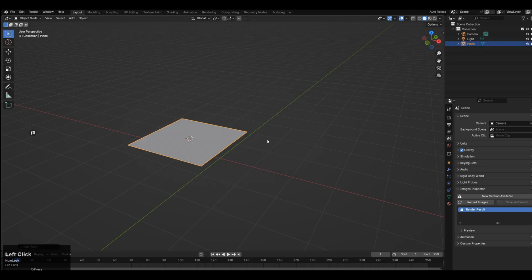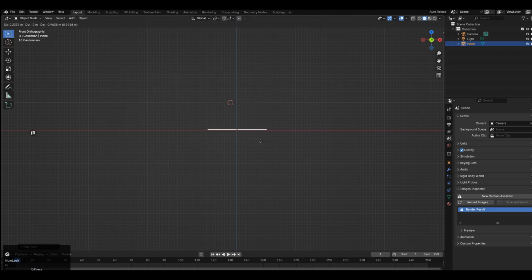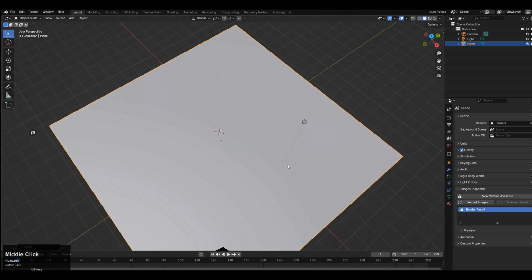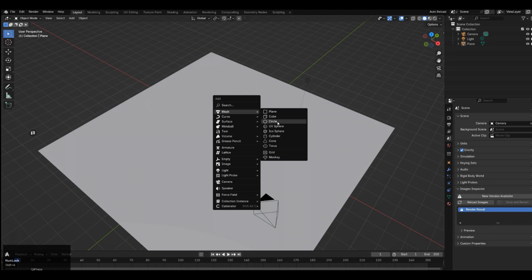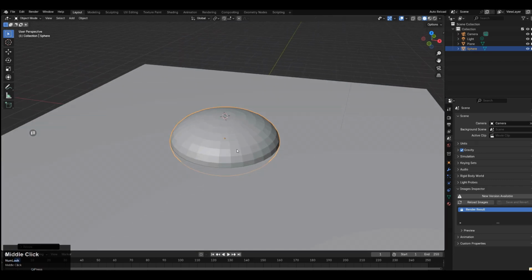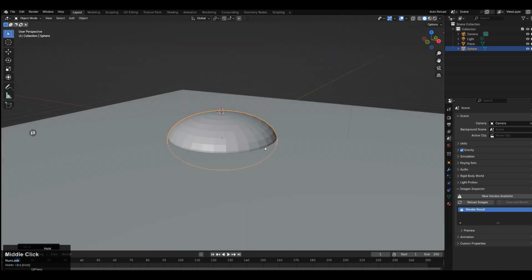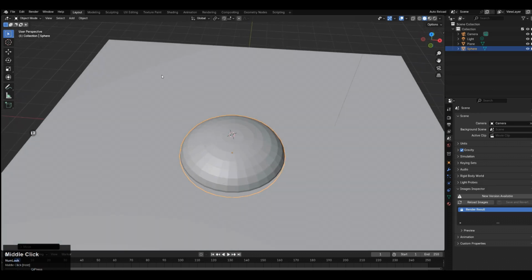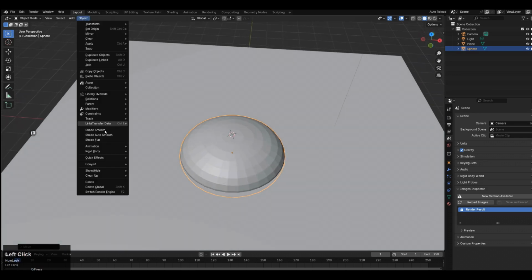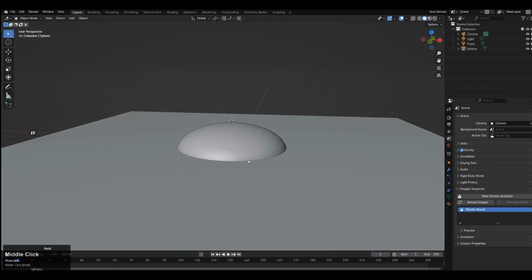Let's go create a plane, Shift A, and pick plane out of the mesh tab. We'll press G, move it down in the middle, press S to scale it, then Shift A to create a sphere. The UV sphere will be our island, and I'm doing super basic shapes here, so it's as basic as it gets. Sink it down into the plane, so it's about our sphere. I do want to make it smooth shaded, like shade smooth, make it look nice and smooth.